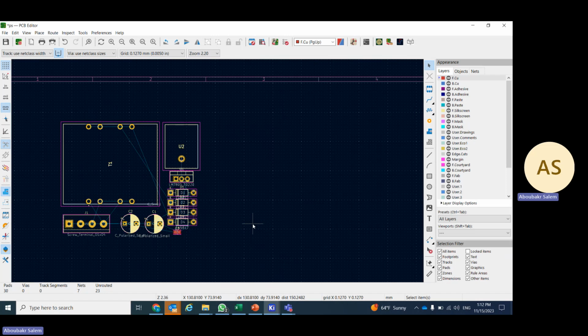But if you have a transformer or coils, regular coil, along with a high frequency element, try to keep it away. Otherwise, there will be interference between the elements, and this will make a lot of noise in your circuit. Okay, noise doesn't mean only sound. Noise means noise on the pulses you have. It will distort your pulses. It may burn some electronic components. Okay, so this is the meaning of noise or disturbance in case of electromagnetic interference.